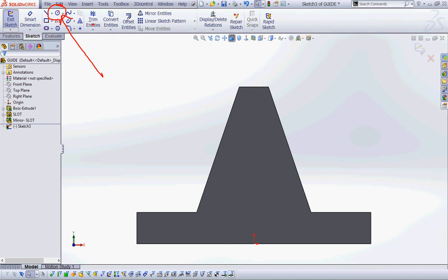This is kind of like the reverse Polish method. I'm selecting the objects before I select the tool, and then I'm going to select mirror right here on the ribbon. Notice it automatically previews, because I've got partial preview, but not only that, it filled in the blanks right away, right? It knew that I was mirroring around the right plane, and it knew what I was mirroring because I had it pre-selected.